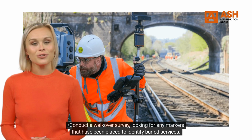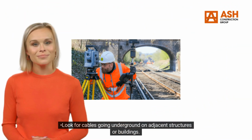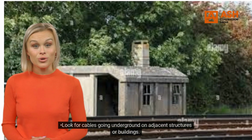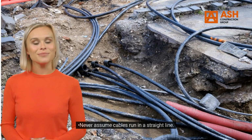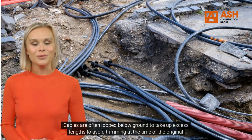Conduct a walkover survey, looking for any markers that have been placed to identify buried services. Look for cables going underground on adjacent structures or buildings. Never assume cables run in a straight line. A cable uncoiled from a drum into a trench will snake. Cables are often looped below ground to take up excess lengths to avoid trimming at the time of the original installation.